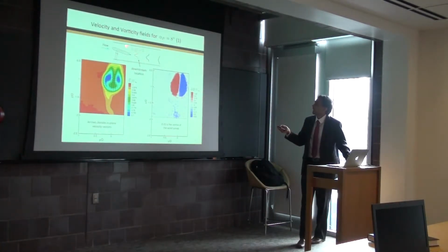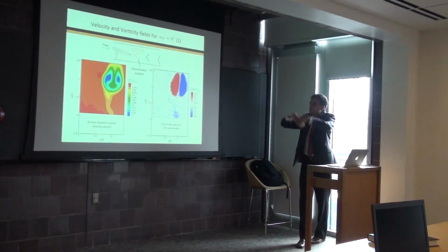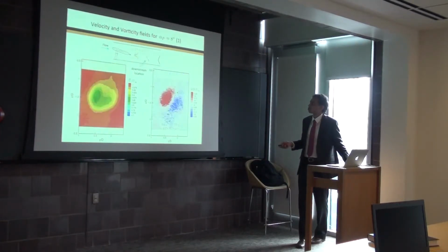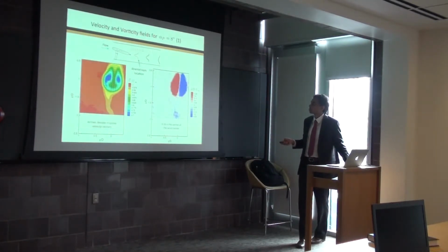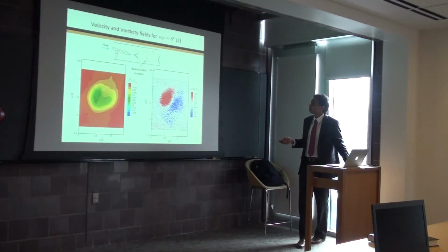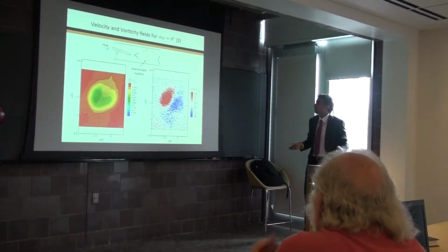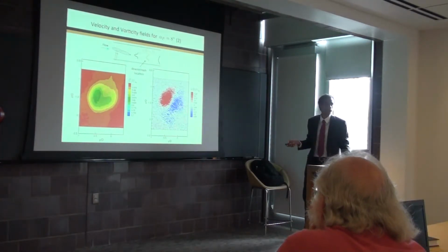So here we look at the wake at 2 diameters downstream. We see this jet of velocity that is being forced between the 2 vortices. These are again those contours of streamwise vorticity that I showed. This convinces you a little bit more of that asymmetry. So clearly there's a precession of those vortices about one another. The vorticity is diffusing rather quickly.